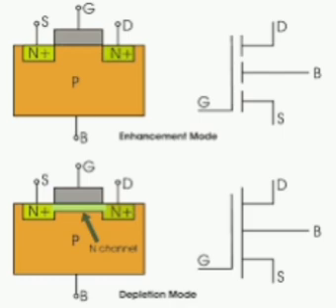Diffusion capacitance or storage capacitance CD. CD is the junction capacitance in forward bias diode. CD is greater than CT always. CD is directly proportional to IF. CD equal to tau into G, where tau is the mean lifetime of minority carriers on either side, or time constant of diode, and G means dynamic conductance of diode. G equal to IF by eta Vt. CD equal to tau IF by eta Vt farads.